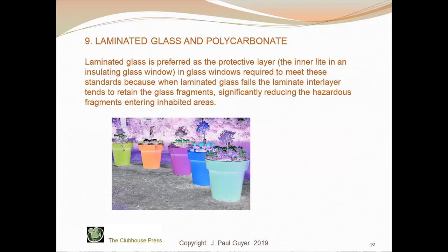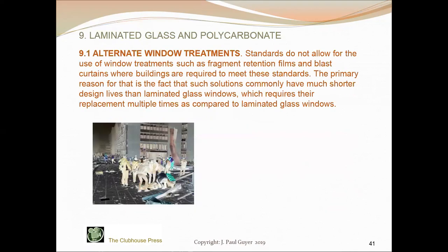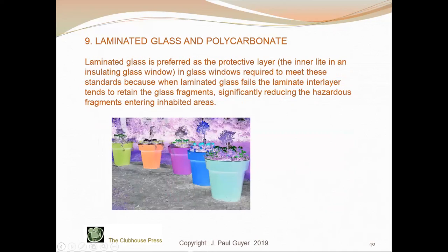Monolithic glass and acrylic are not allowed by these standards because those glazings break into hazardous fragments. Polycarbonate or other glazing systems that can be shown to provide the response required by these standards are allowed because they limit fragment hazards.